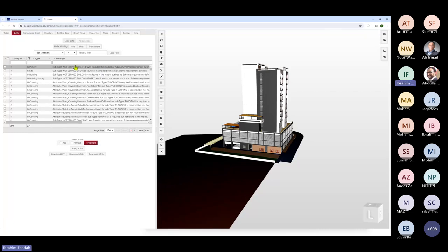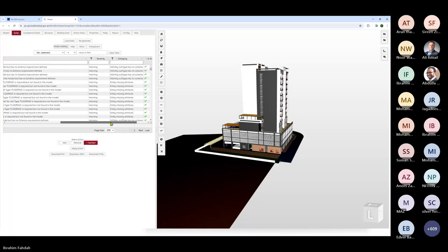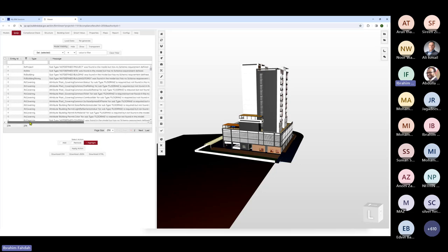The tool will go through all the IFC files and gather any violation in terms of data quality and produce a list that you can download locally. You can produce it in different formats, Excel format is one of those. What is important as a quick test to make sure things are fine is to make sure there are no critical and error type issues here. Now, because Aaron did the model correctly and followed all the standard requirements, all these issues are just warnings to bring attention to potential things.